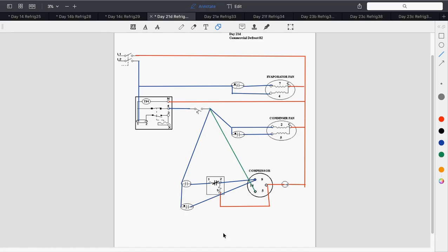Now, if I had a defrost solenoid, which is hot gas, would I want to be shutting off the compressor and the condenser fan? I'm going to say no. Yeah, because I need to have the compressor to give the hot gas. The only thing I would be shutting off would be my evaporator fans. As soon as you go to a powered defrost, we have to shut our evaporator fan off and defrost. Make sense? Yeah. Okay.